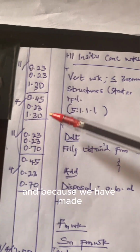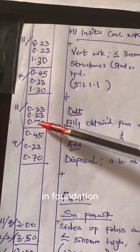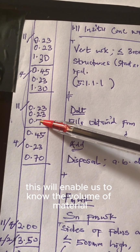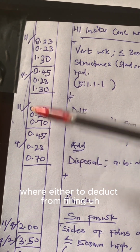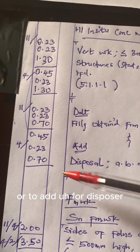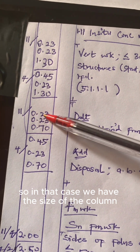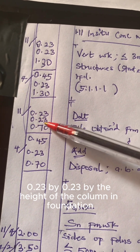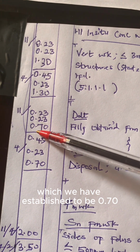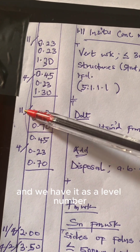And because we have made provision for the height of this column in foundation, this will enable us to know the volume of material we are either to deduct from filling or to add for disposal. So in that case, we have the size of the column 0.23 by 0.23 by the height of the column in foundation, which we have established to be 0.70, and we have it as 11 number.